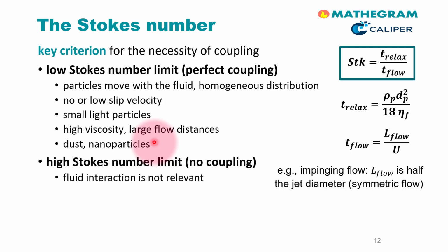The other relevant limit is the high Stokes number limit, for which no coupling to the fluid is necessary. The simple reason is that the fluid interaction forces are not relevant and the deflection of the particles is only insignificant due to the fluid motion.